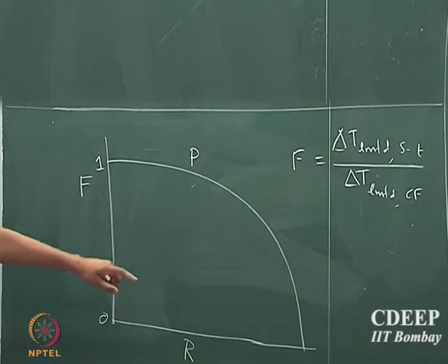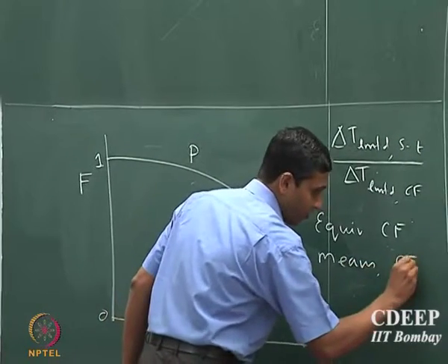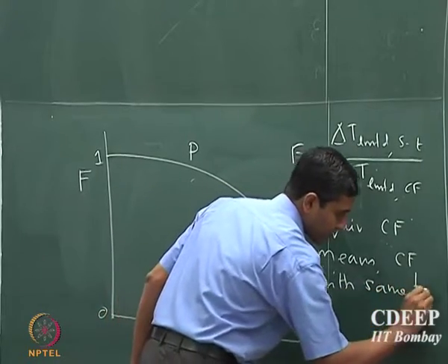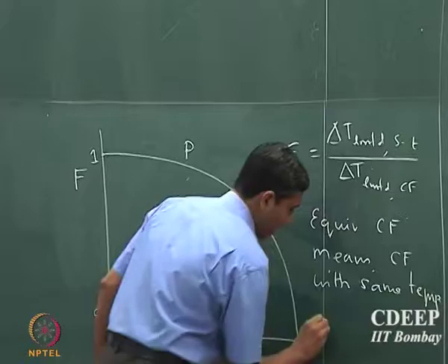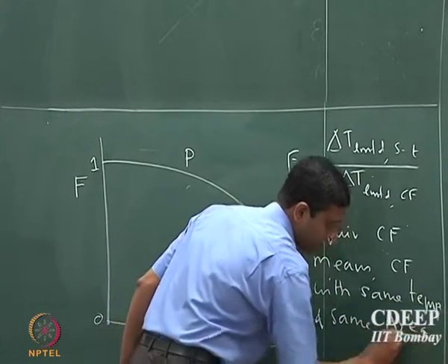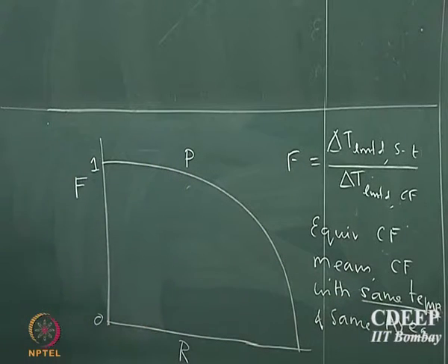The same temperatures, you just have a counterflow configuration, that is all. The area is the same. So, the net heat transport area that you have is matched with the corresponding counterflow area. So, what it means by saying equivalent counterflow is with same temperatures and same area, that is very important, same temperatures and same area.